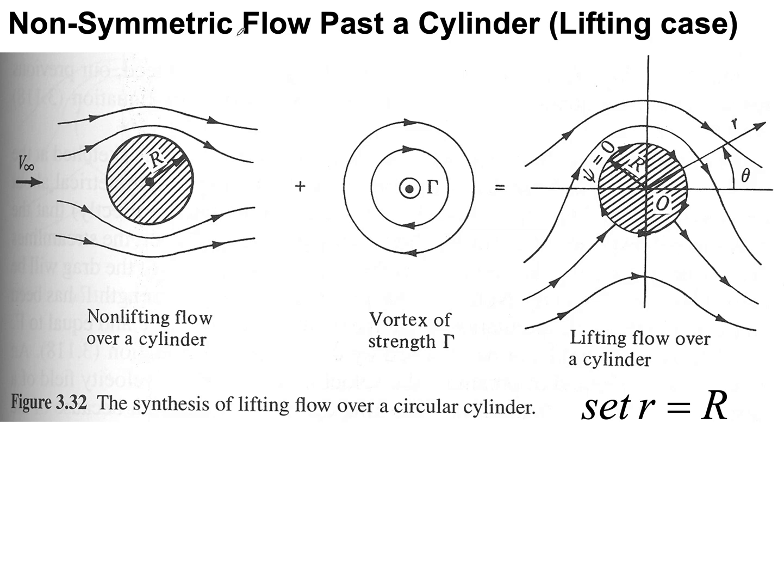So now let's sum up the uniform flow and a doublet that gives us the flow around the cylinder, and then let's add some rotation to it. So let's add a vortex on top of that cylinder. When I add a vortex, my cylinder is going to start to rotate, and it's going to mess up my streamlines. It will make the streamlines on top go faster, and on the bottom, because that is opposite to that over here, it's going to subtract, while this guy is going to add up to this guy, so it's going to move faster on top and slow down on the bottom.